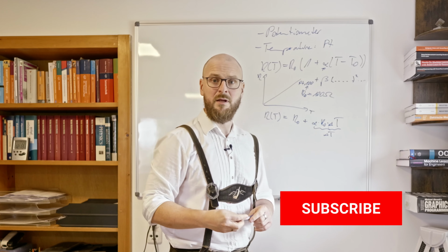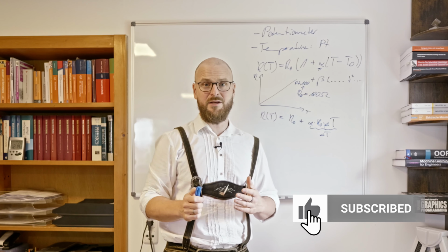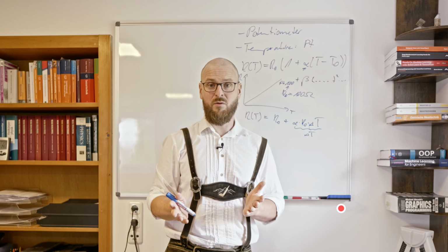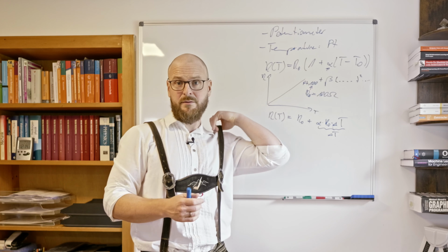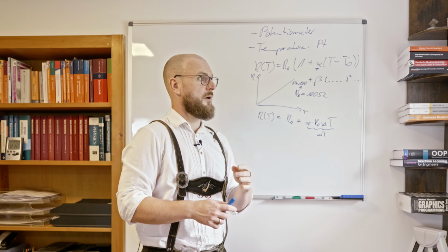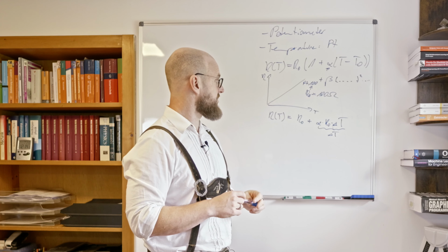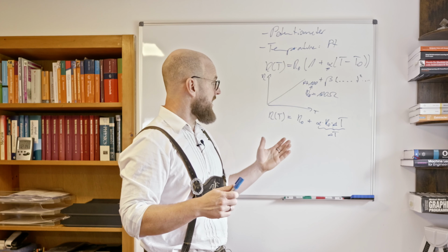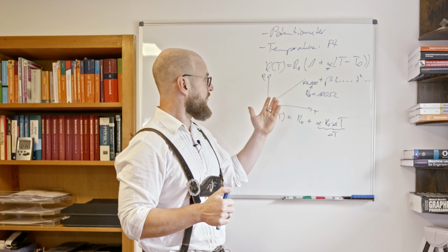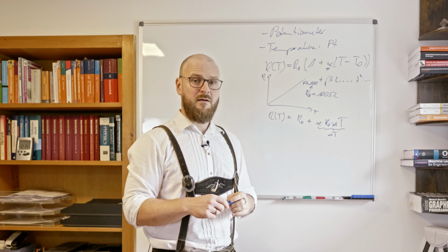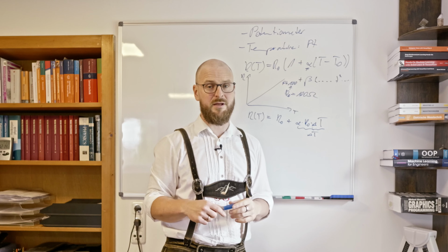Talking about platinum, changing the temperature about 10 degrees will change the resistance by about 1 ohm for a PT100, which is quite measurable. It's not too hard to measure that resistance change, and which is enough to make those resistance temperature sensors very widespread and very used out there in industries and any which way.